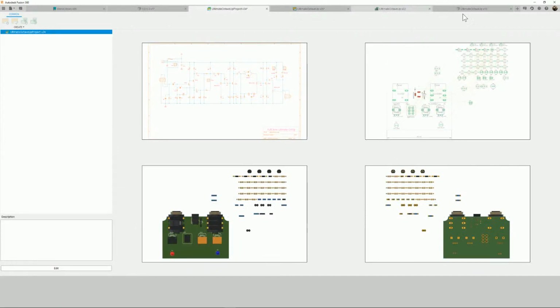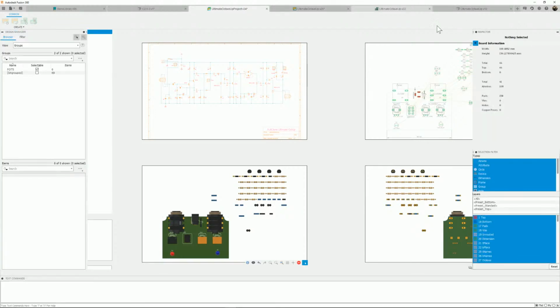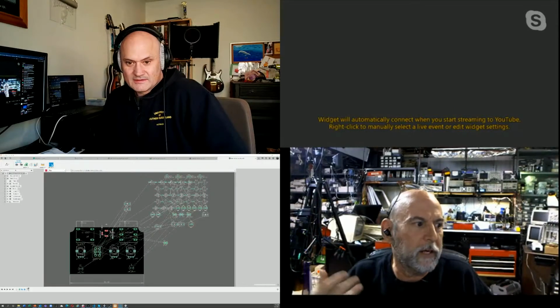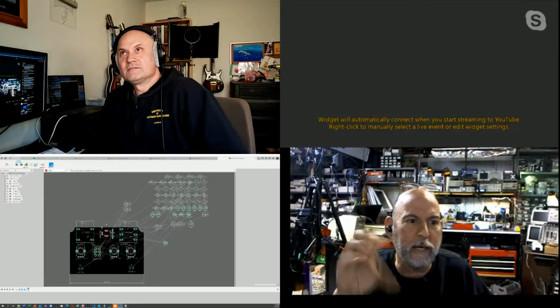Now the problem I have with Altium, if I want to bring in a part but I don't want it to make suicidal connections, on other CAD systems you can lay it off the sheet to the right or left or something. But Altium says, no parts off the sheet. So I don't have a scratch area, and I never did use the buffers like they talk about. You know how you could have multiple paste buffers.